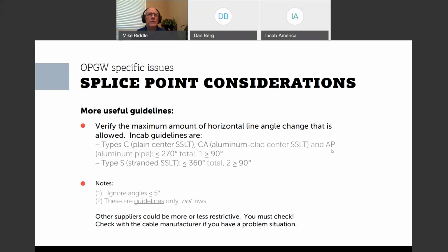The reels should be double chained down to the flatbed, and the reels should also be chocked. And then maybe the question they're wondering, do the reels need to be tarped or covered? My answer is no, they don't. Wood reels or steel reels shouldn't need to be tarped.